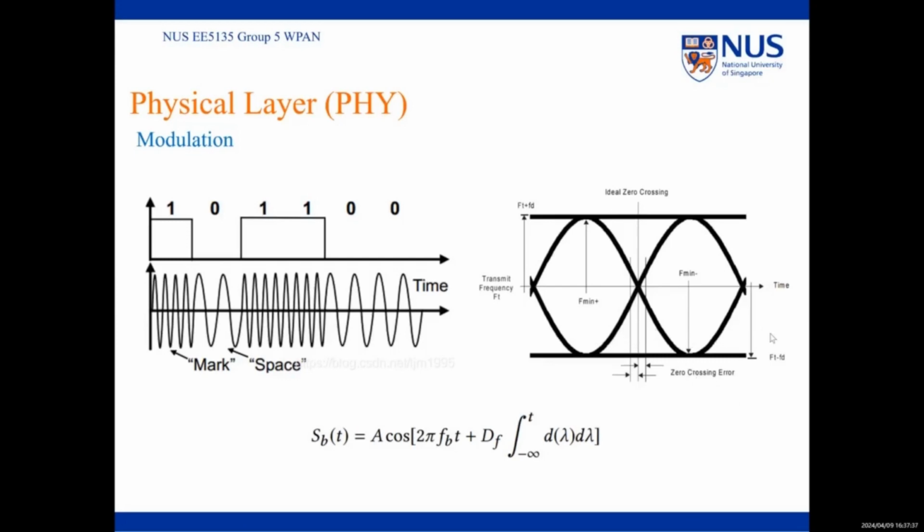Gaussian frequency shift keying (GFSK) is a modulation method used in Bluetooth communication. Unlike traditional frequency shift keying, GFSK applies Gaussian filtering to the original data before modulation. This filtering reduces the signal strength at frequencies other than the desired modulation frequency, minimizing interference between different frequency signals. In GFSK, the carrier frequency is shifted to encode data. The positive frequency deviations represent a binary 1, while negative deviations represent a binary 0.